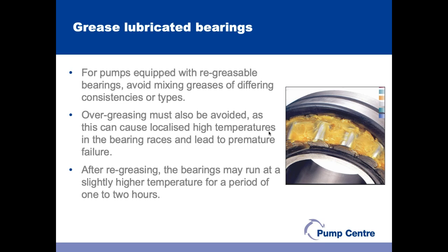So it is a fact, though, that after putting new grease into bearings, or possibly adding some more grease with a grease gun, the bearings are likely to run at a slightly higher temperature for a period of 1 to 2 hours.